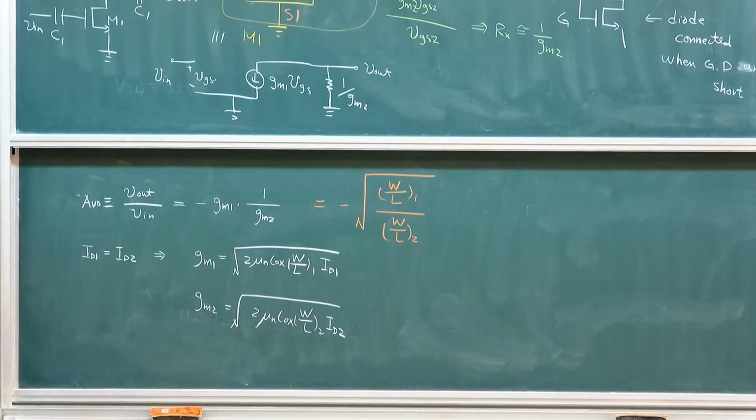What I mean by this is that if you're looking at the left, this particular amplifier, if my current changes, meaning even though both of them, gm and ro, depend on current, therefore, this will not be a linear curve. I could only say that the slope depends on this, but the slope changes across the region. So that means that there will be a little distortion on my amplification.